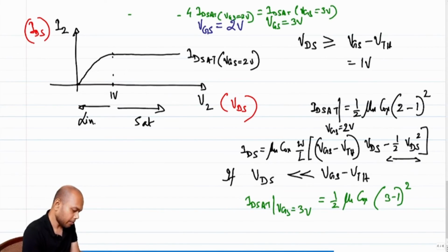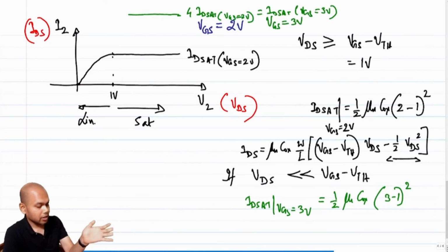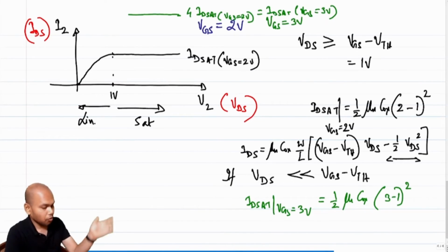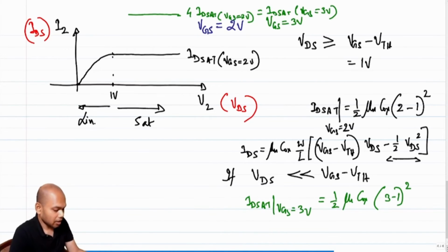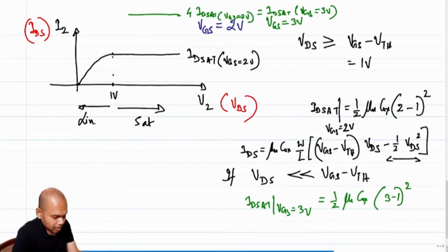So this again will be constant, but now till what voltage will this be constant? What voltage of VDS will this be constant? In other words, I am asking what is the limit beyond which you have the demarcation line of saturation region and linear region.